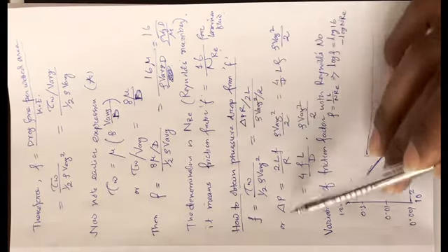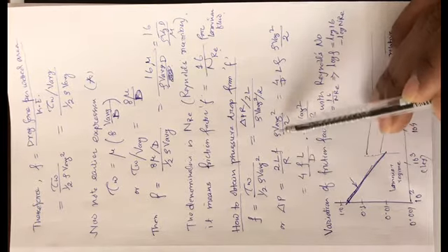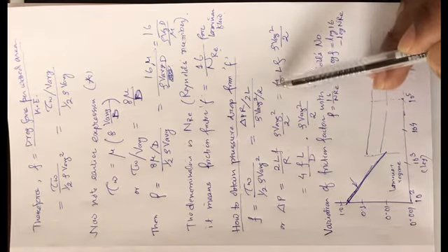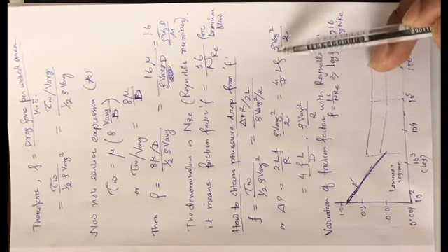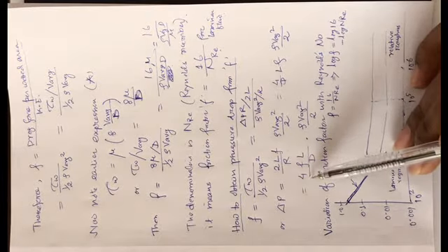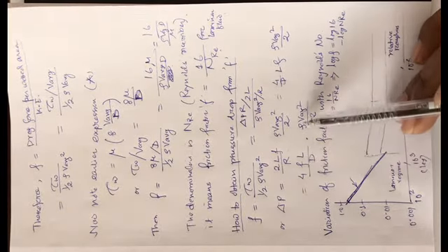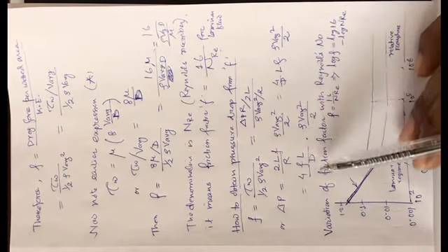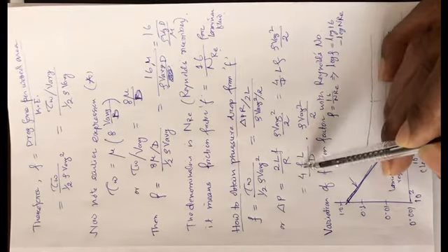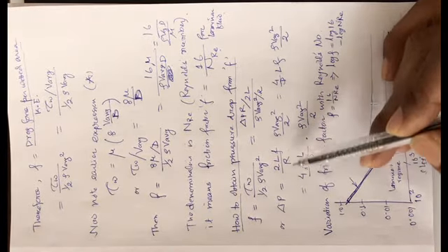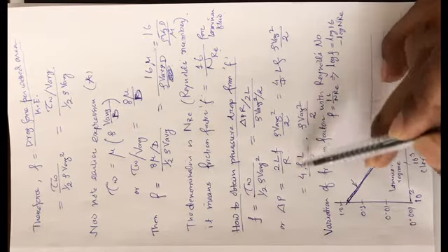So the pressure drop we can write as 2FL by R times kinetic energy, which is 4 by D, so 4FL by D into the kinetic energy term. So if you know the value of friction factor, then you can estimate the associated pressure drop.